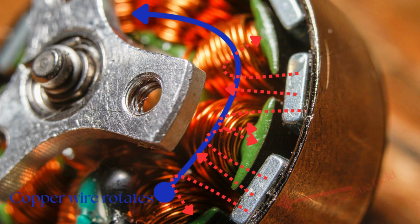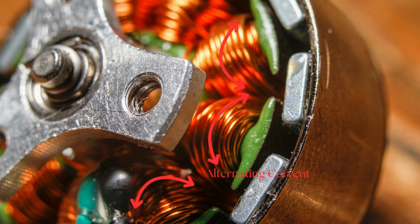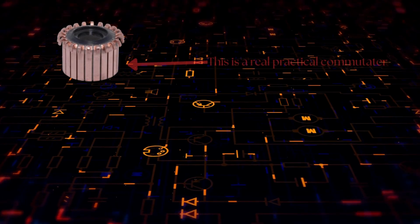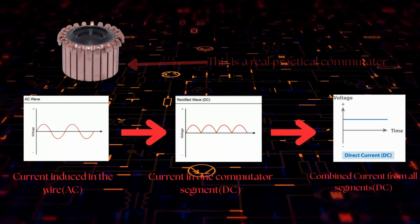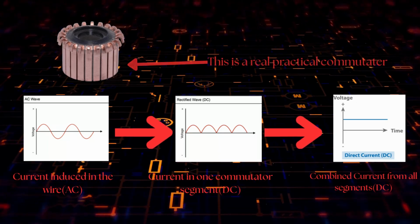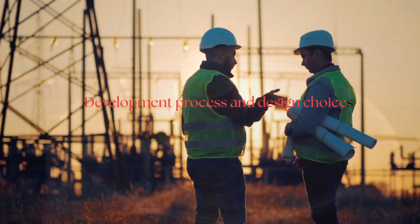The copper wire on the shaft moves through a changing magnetic field created by the permanent magnets. This induces an AC current in the wire, which is then converted to DC through a commutator. A commutator does this by reversing the current produced by the coils every half turn, therefore only allowing current to flow in one way. The direct current can then go and power the small light bulb.